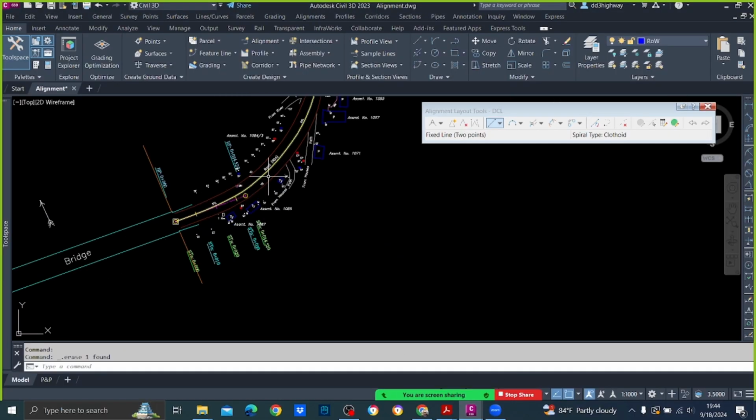If you are going to give 7% super elevation here, you can't suddenly give super elevation. You have to gradually increase it. So your super elevation development will come into the bridge, and that is not permissible, because you cannot have super elevation changes in the bridge. So that means you are going to put your structural colleagues into trouble.